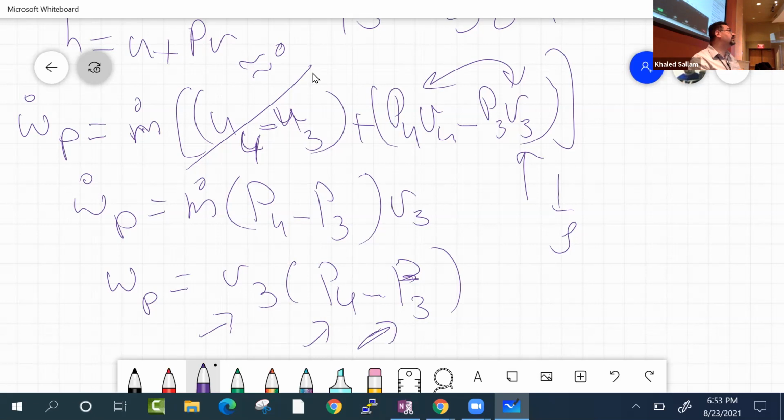And this is embarrassingly very accurate, to a few digits, pretty good. It's the same as getting the entropy and the pressure, reading the H and subtracting it from the other H. You get the same thing, just by saying P minus P over rho. Why? Because the density does not change that much and the water does not get that hot in a pump.